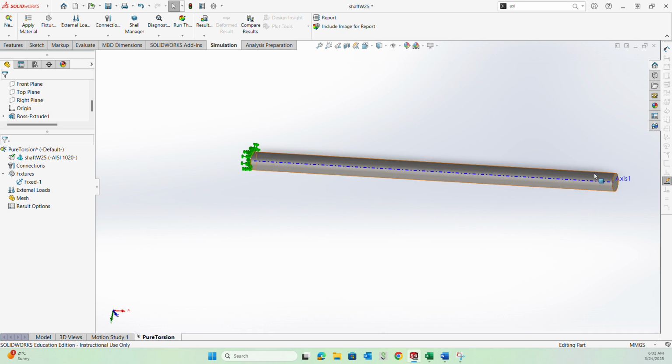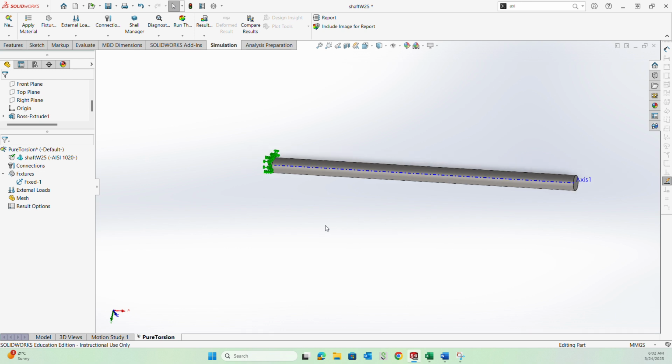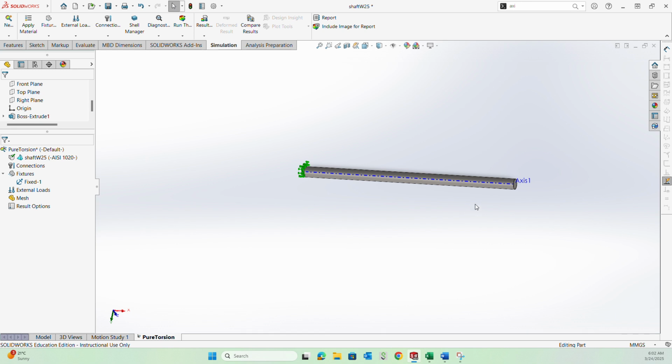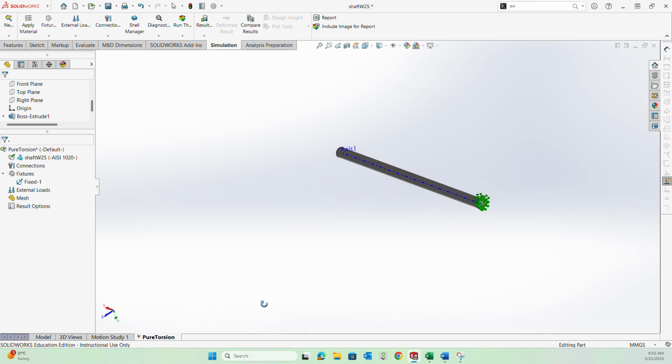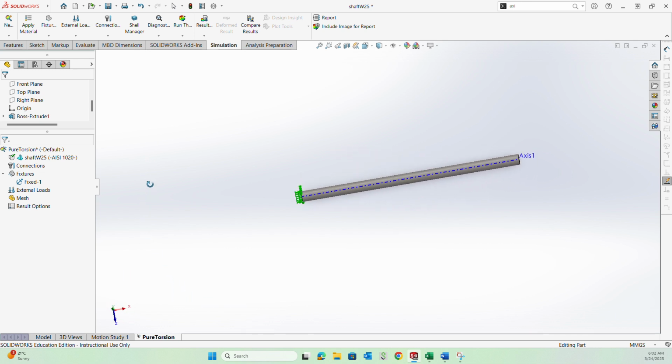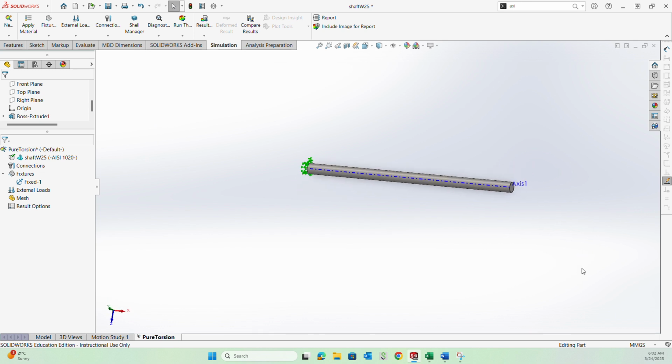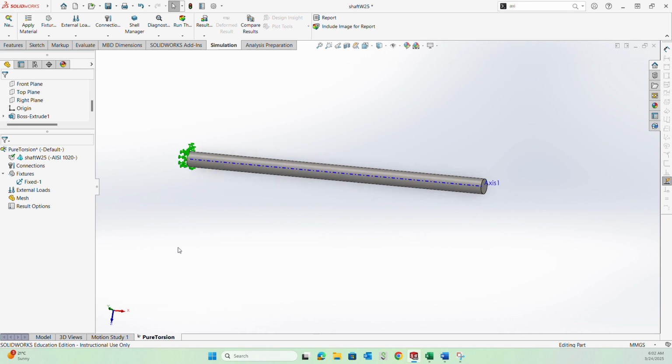But if you apply the torque on this end without any further constraint, this is free to flex about the long axis as well, so about the z axis, and therefore you will have flexural stresses in the beam if you do not put any further constraint. Because of the rod's self weight, that will not add significantly to the stresses, but it will add some stresses.